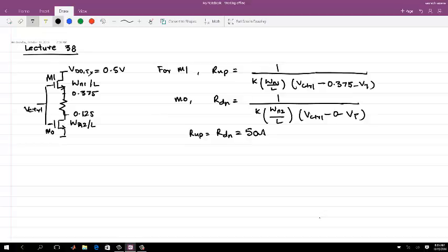Overdrive for RTN will be the same, right? So if you are looking for that particular variation, this is one of the drawbacks of this N over N output driver: unless you use a different control voltage for M1 and M2, you cannot maintain an independent 50 ohm impedance.